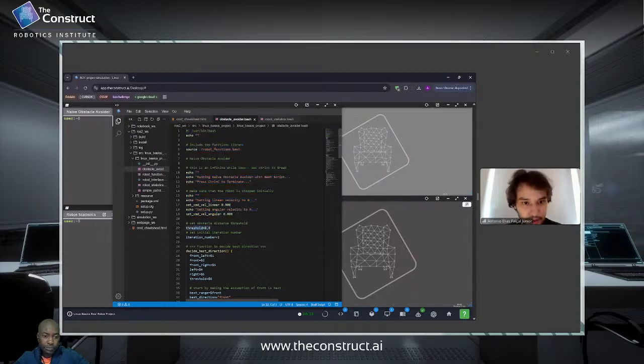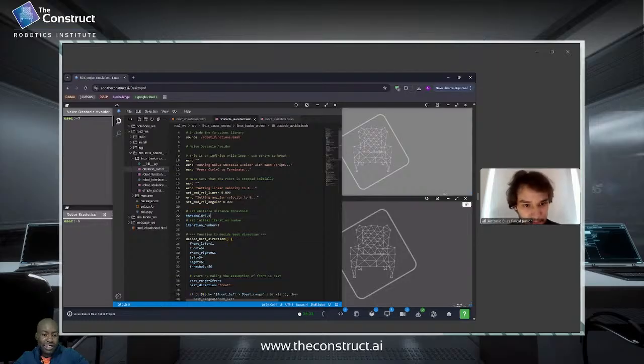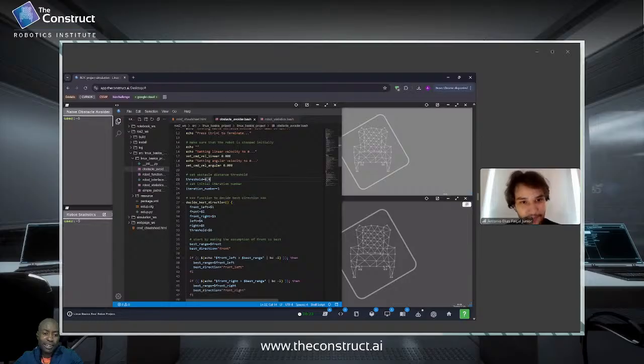This is the hard threshold for detection that I mentioned. Why did you not use 0.3? Did it crash when you used 0.3? Not necessarily, but I felt like the threshold being 0.4 prevented some rotation errors. Like it would touch the wall, rotated less. So when you used 0.3, it ended up rotating more to clear either the left or the right? Yes. Okay, all right.